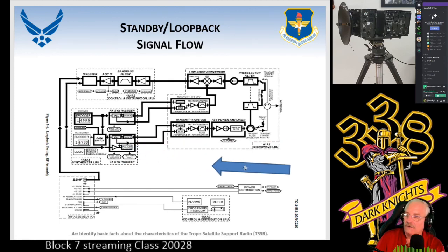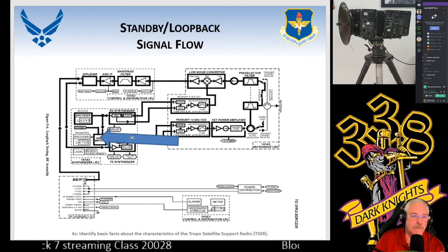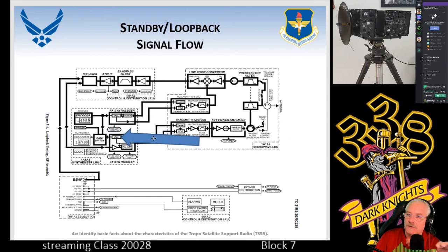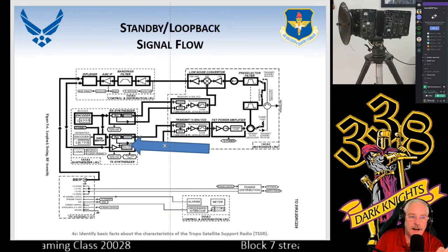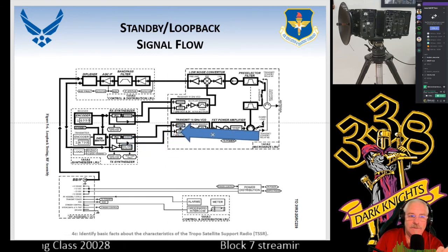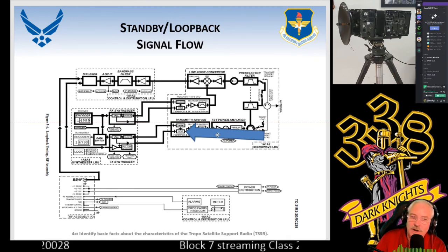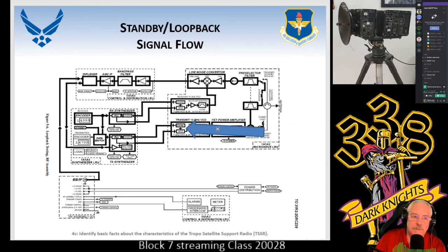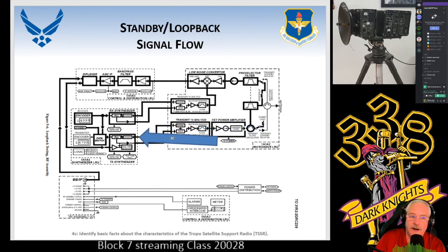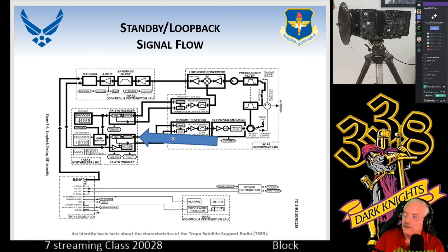And for those of you trying to figure out what phase lock loop is, well, when the data switch tells the phase lock loop what to do, it's going to send a voltage down this line up to the VCO. That voltage is going to tell the VCO what frequency that you need to be on. Well, you'll notice that a portion of it goes up to a divider and then comes over to another divider. And what it's doing is it's generating a square wave frequency, or representation, of the VCO.